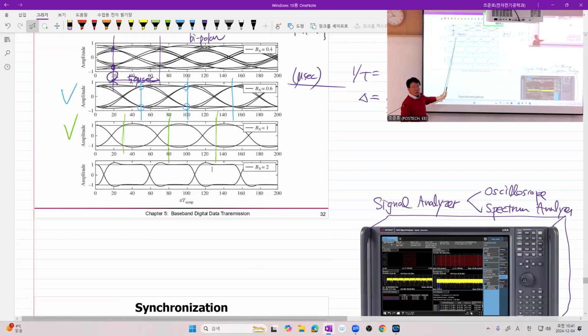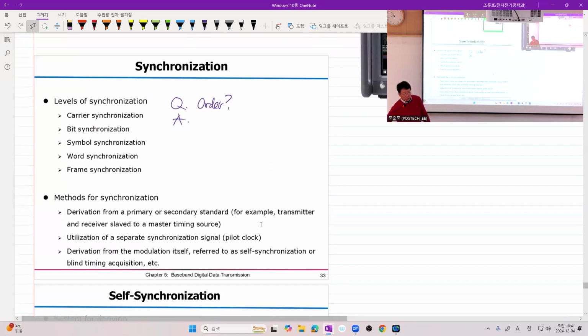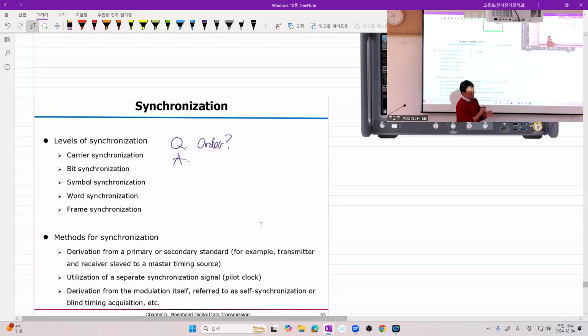And see that again here? Which one is the first symbol? It depends on the delay introduced by the channel, right? We never know just by observing the signal. So usually in digital communications, we put some markers, some short known vector of symbols, in front of a packet or a frame or word, something like that.